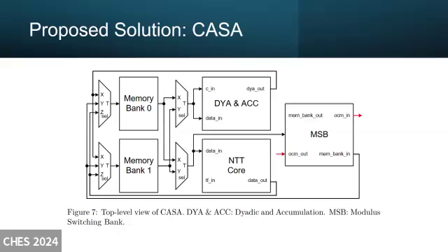The reason we designed this kind of format is that multiple operations can be executed at the same time, while also taking care of the pipelining and the scalability. You can see that we use 4 3-to-1 muxes to switch the memory banks.